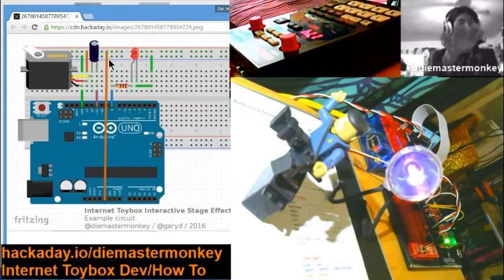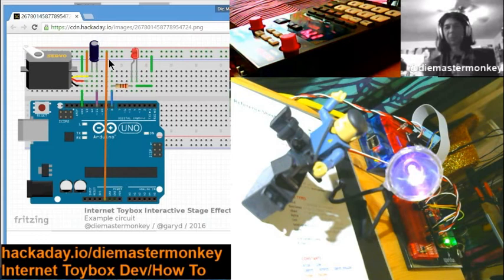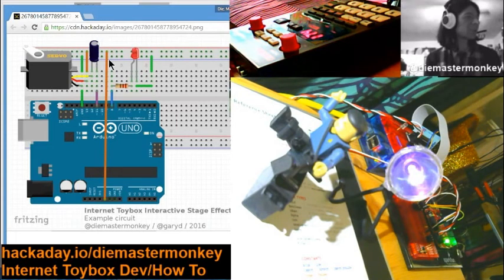It's meant to keep the voltage and current in the circuit from fluctuating when a servo suddenly draws a lot of power. Although I think the nice servos have that circuit in there already. In any case, you can get by without one, but you shouldn't.